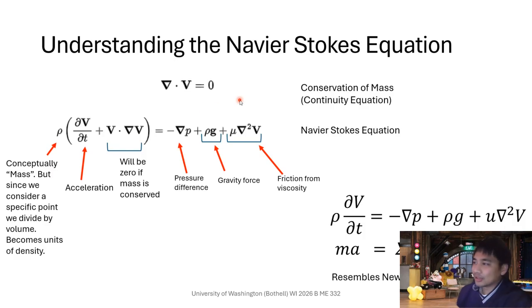Okay, so conceptually, the Navier-Stokes equation is kind of just two equations that are satisfied, which are pretty fundamental laws of physics, right? So you have your conservation of mass. In parentheses here I put continuity equation because the textbook refers to this as continuity. But I do not want you to get confused with your Q equals AV equation, which is in a way also conservation of mass.